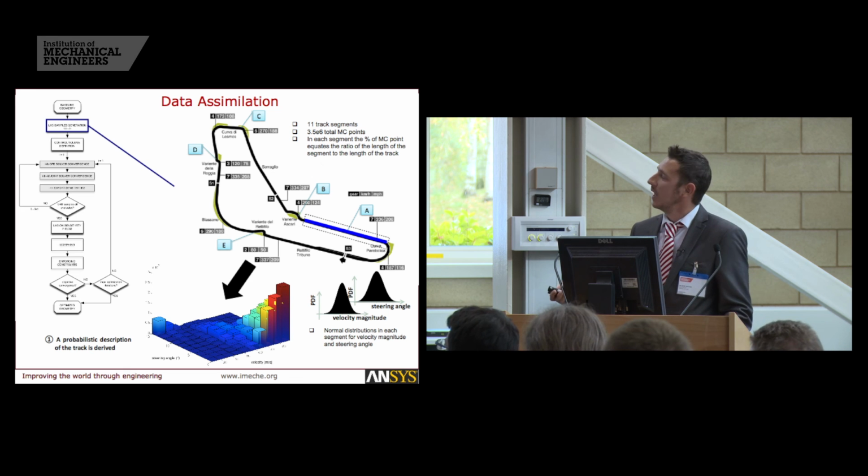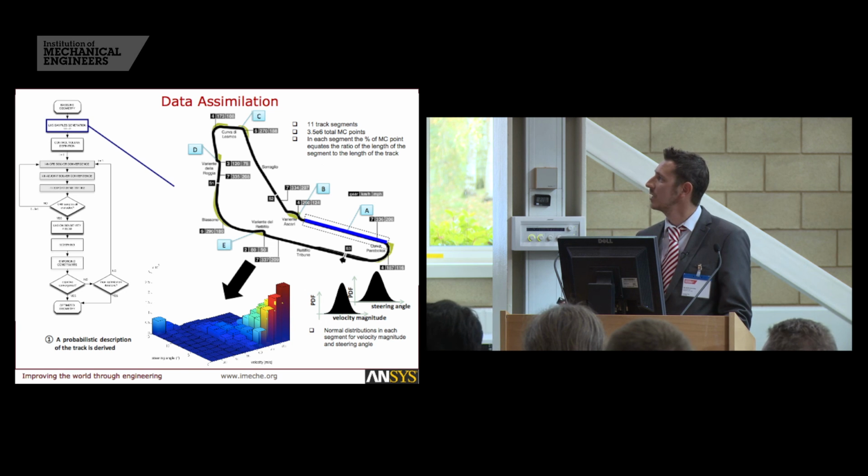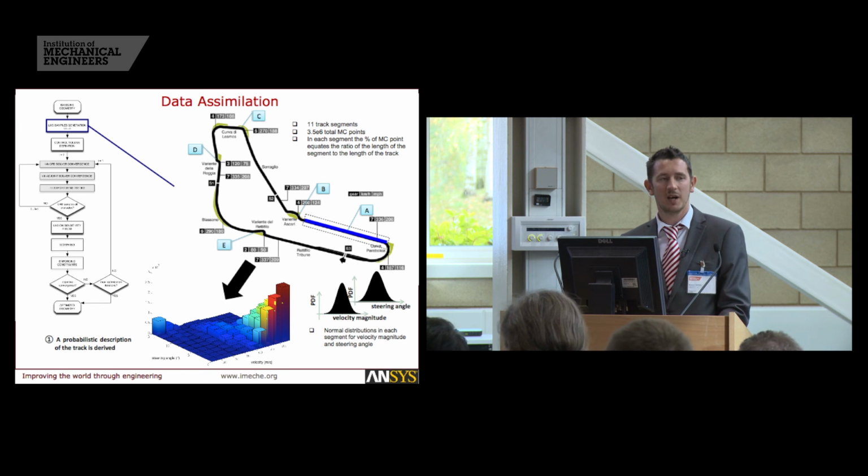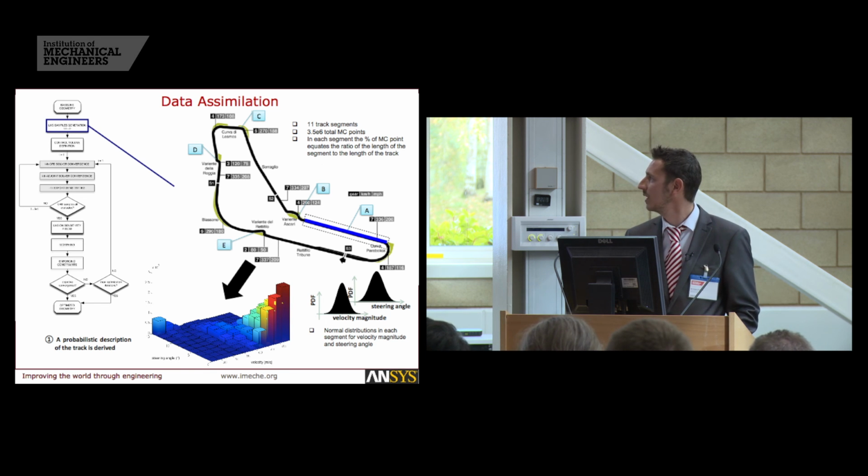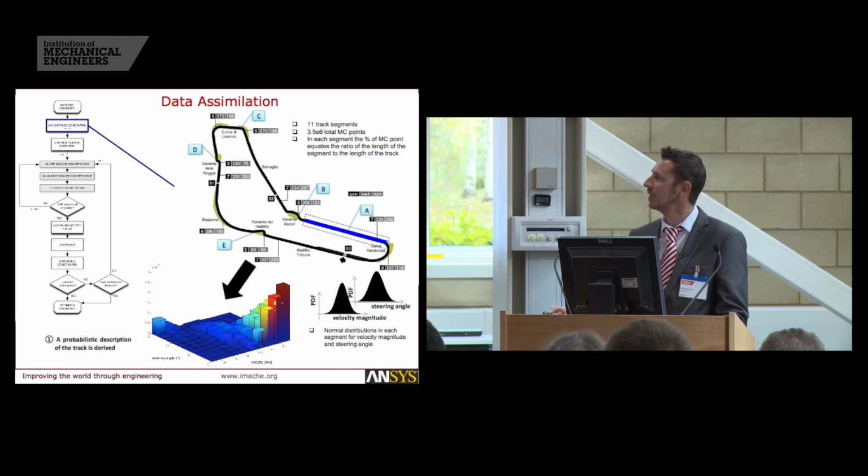So here what we've done, again, we've used a sampling process. Instead of Latin hypercube here, we have a larger number of points, and we've used a simplex stochastic collocation approach in this particular case. But the approach is still the same in terms of the sampling points that we use. We apply a morphing box, similar to that you would have on a legal box constraint on a front wing. It restricts the amount of movement within this particular zone. And we also define a number of control points, and this will also affect the available morphing as well.